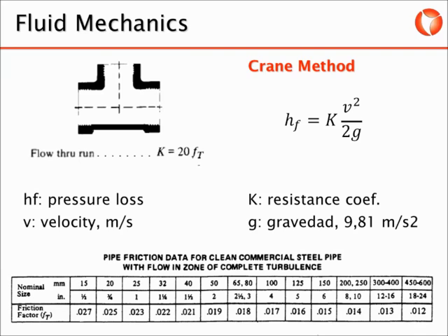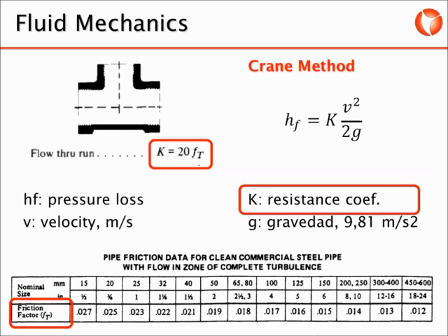Based on numerous laboratory trials and geometric likeliness of different fittings, this method establishes the friction factor for different sizes of new commercial piping, then a resistance coefficient for each fitting can be obtained. That, combined with Darcy's equation, yields the pressure loss of the fitting. The great advantage of this method lies within the programming possibilities, saving considerable amount of time.